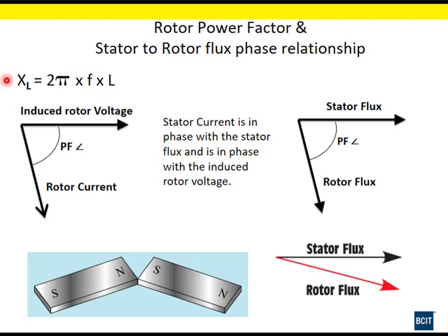The rotor power factor and the stator to rotor flux relationship are pretty critical to understand how the speed of the rotor is going to affect the torque. We already see how the inductive reactance in the rotor is going to be affected by the change in frequency in the rotor. As the frequency increases or decreases, the inductive reactance is going to follow.